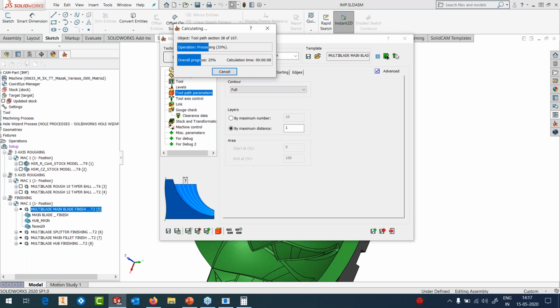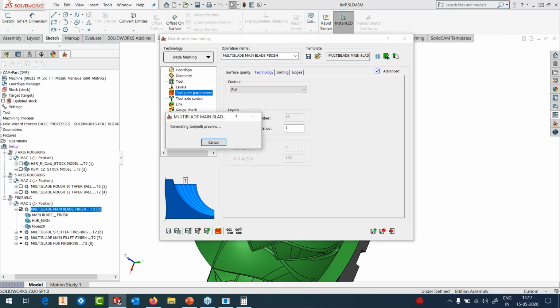Somebody's asking what kind of parameters to take into account when you're machining such parts. First of all, you have to really listen to your tooling people. They know much better when they are handling such parts. So the RPM, feed rates, depth of cut, and side step need to be taken. And please use specialist people who know what impellers are, and not somebody who just sells solid carbide end mills. No, this is a specialized function, and it needs special care, special support. So use the help of those people who know these functions very well. Okay, so take those parameters. The most important thing here are the parameters.